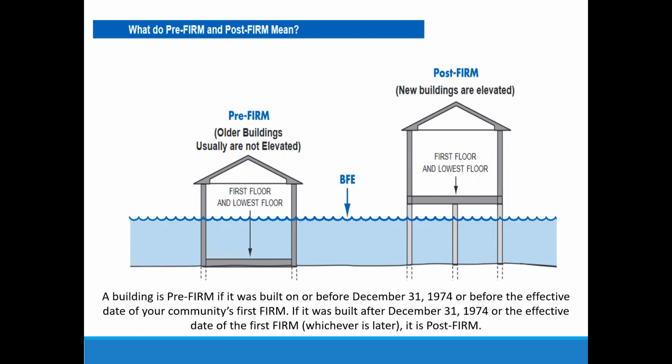And so hopefully a post-FIRM structure has been built, properly elevated, and considering more of the flood potential damage that could happen. As I mentioned, in Kansas, a lot of structures have had basements because they were worried more about tornado safety than floods. In that way, FEMA really recommends safe rooms, definitely more than a basement. That's a separate issue, but theoretically, a post-FIRM building is elevated.